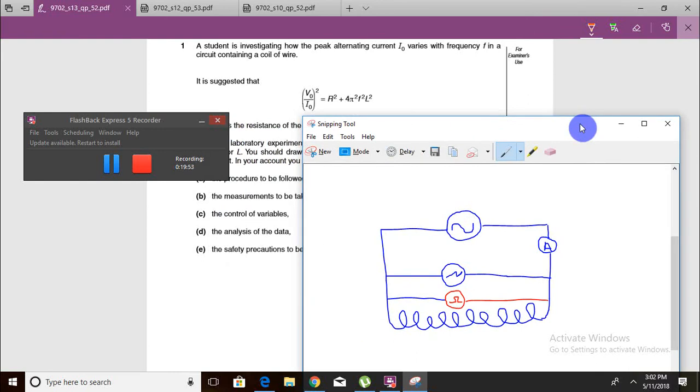Procedure: use a signal generator to keep the value of the peak voltage at a constant value while changing the value of the frequency within a range. The value of the V out and the value of the frequency can be read from the oscilloscope to see if they have changed by the amount we intended them to change. If the oscilloscope is properly calibrated with the help of a time base, there will be a trace on the oscilloscope and there will be horizontal and vertical displacement. The vertical displacement will show the voltage signal and the horizontal displacement will show the time.